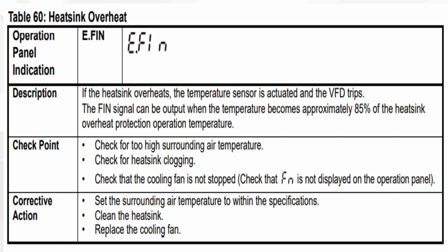One, the fan is not working properly. The heatsink might also be too dusty, so we have to use a blower to clean the inside of the VFD. There could be one more reason: the environment could be overheating, like you have placed the VFD in an environment where there is too much heat. If the fan is faulty, we have to replace or repair the fan.